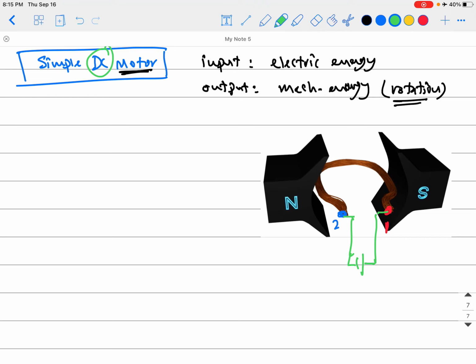Okay, so rather than rotating this coil inside the magnetic field and expecting to have induced voltage in it, now I'm pushing voltage to it from an external electric source. Okay, so rather than like this, you will have current moving, electric current through here, so you have current moving through the coil. So the current will be moving inside the coil like this, and coming back from here. Okay, guys? And you still have the magnetic flux going from the North Pole to the South Pole like that. So we are now having everything we need to have a motor. We need electric current to move through a coil while cutting a magnetic field. So now we have everything in hand to have a motor, okay?